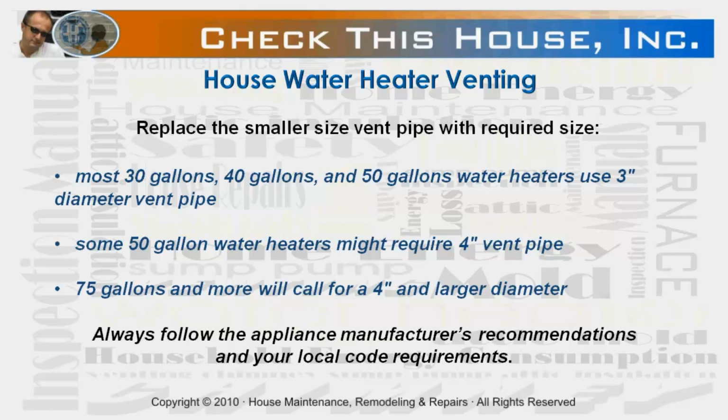Remember to always replace the smaller diameter vent pipe with one that matches your new appliance requirements. For example, most 30, 40, and 50-gallon water heaters are using 3-inch diameter vent pipes. Some 50-gallon water heaters might require a 4-inch diameter vent pipe. 75 gallons and more will call for a 4-inch and larger diameter. Always follow manufacturer recommendations and comply with your local code requirements. Again, never downsize the vent pipe.